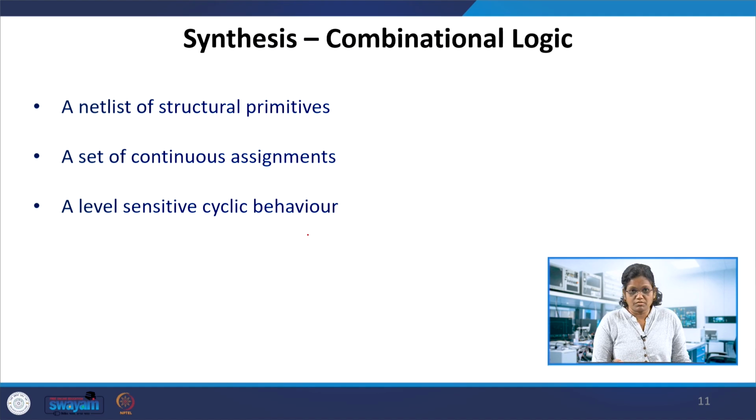And level-sensitive cyclic behavior, here cyclic means always @(A or B), not the posedge or negedge of the clock, but level sensitive, A is 1 or 0, B is 1 or 0. Those kinds of structures in Verilog modules are synthesized into combinational logic. So combinational logic is not only the structural one; the level-sensitive behavior of an always block with all the inputs in the sensitivity list, for example A, B, is also synthesized into combinational logic, and continuous assignments as well.